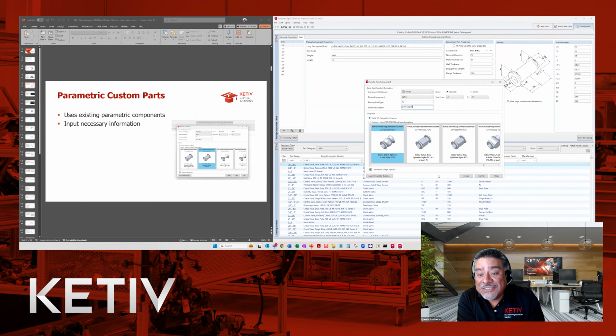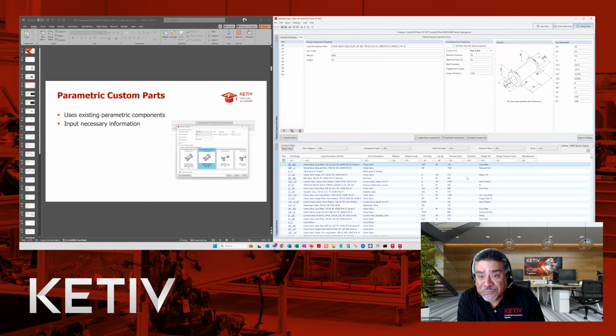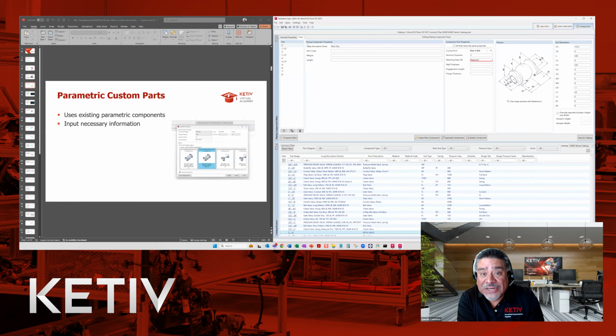So if I get those selected, then I can go ahead and create. And if you notice, it jumped over here and pulled in this item, which is the one I selected. Then there are some different tabs here for this particular component that I created. And if you notice down here, this is where it was added to. It did add it to this ASME valves catalog. If you wanted it in a different catalog, you could have selected a different catalog for it to be placed in by making sure that was open down here first.